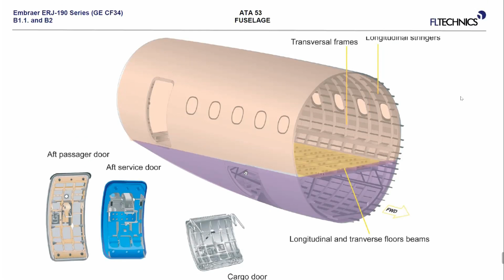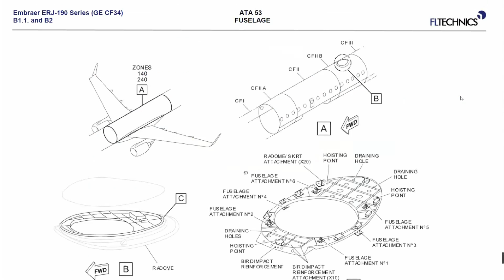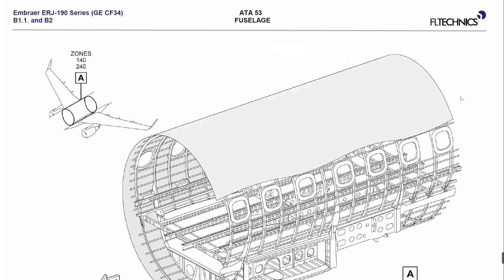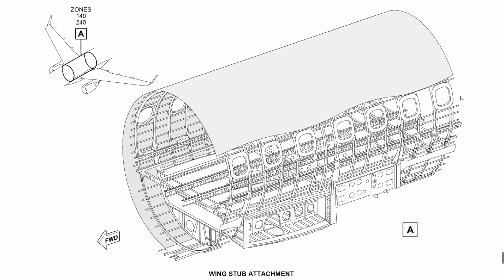The only special is when you talk about center fuselage 2, because we have many differences here in the construction. Keel beam, we have the wing stub, additional half pressure bulkheads, you see? Below the floor structure, we have many differences.